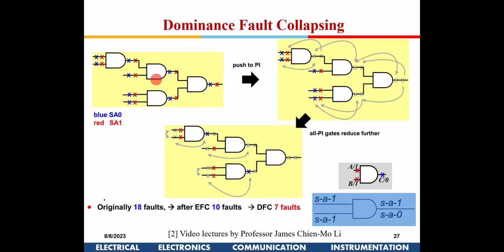Right. So what the algorithm does is, first all the faults are there, right, and from here it is moved towards the input. As you move, it is shown. So finally you have everything at the input. Once you have everything at the input, then these two red, can they be moved as a single one to the output? No. But can the blue be moved here? Blue is stuck at 0. Can it be moved here? Yes, sir. Yeah, because that is equivalence, right?